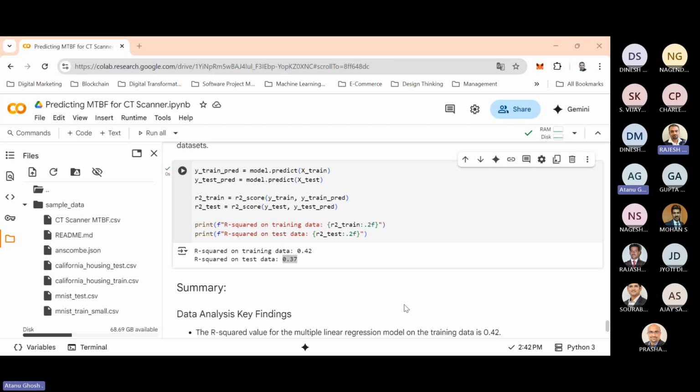At the end, I finally test that part. While testing, I am getting some pseudo rejections. That means the part may be okay but has got rejected. So Type 1, Type 2 errors. What our problem here is, we have to identify which process is creating this outcome, whether this is a pseudo rejection, okay or not okay.